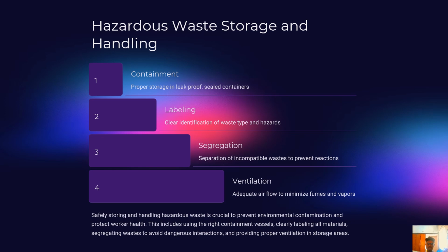Safely storing and handling hazardous waste is crucial to prevent environmental contamination and protect worker health. This includes using the right containment vessels, clearly labeling all materials, segregating waste to avoid dangerous interactions, and providing proper ventilation in storage areas.